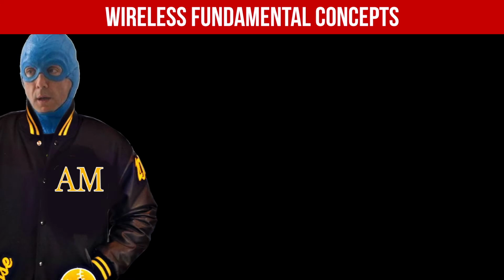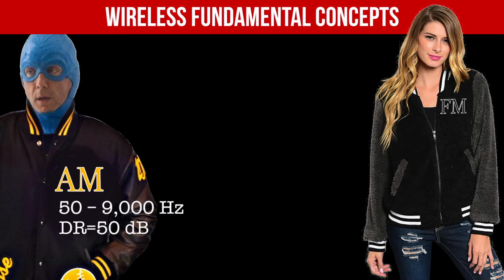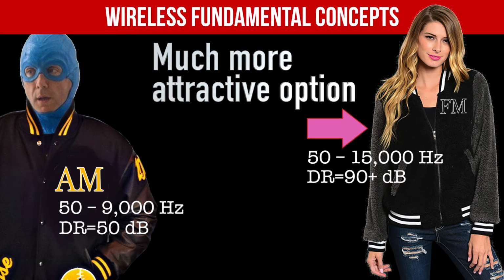Amplitude modulation systems are less common than frequency modulation systems. The actual specifications of the AM system are limited. Considering the maximum legal modulation, the usable bandwidth is between 50 and 9,000 Hz, and the maximum dynamic range is about 50 dB. A frequency-modulated radio signal uses a constant amplitude carrier at a specified frequency. Almost all modern wireless systems utilize this FM principle. Its potential for high-quality audio transmission is much greater than the AM principle. The maximum legal deviation from the carrier frequency provides for an audio frequency range between 50 and 15,000 Hz and a dynamic range of more than 90 decibels.